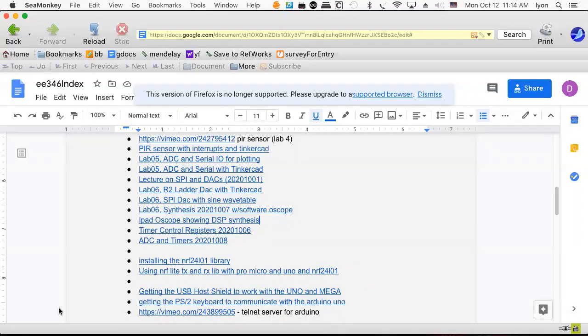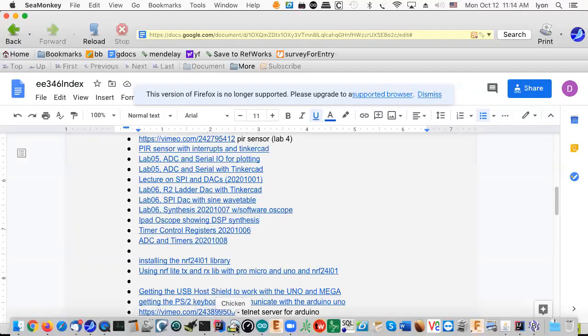You can synthesize that without using trig functions at all, and you don't have to worry about using multiple CPU cycles to compute something like a trig function, because that stuff is double precision floating point, and there's no way your little 8-bit toaster controller is going to do that in one CPU cycle.